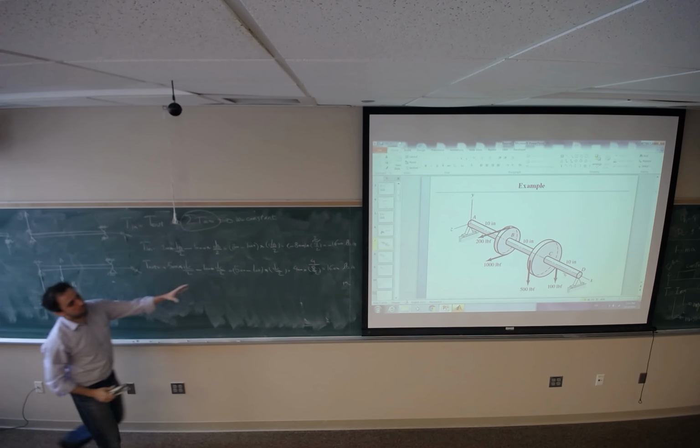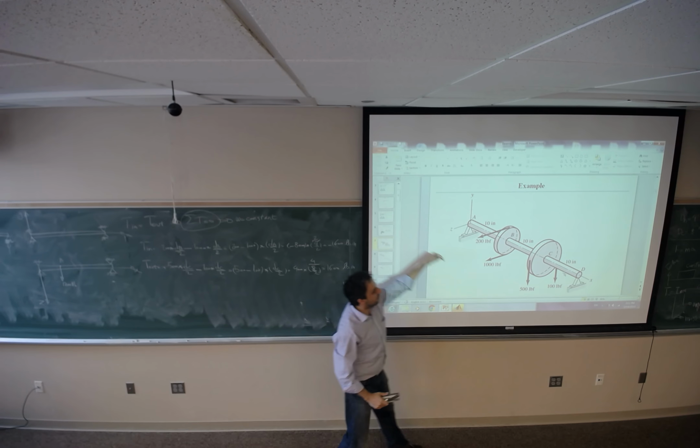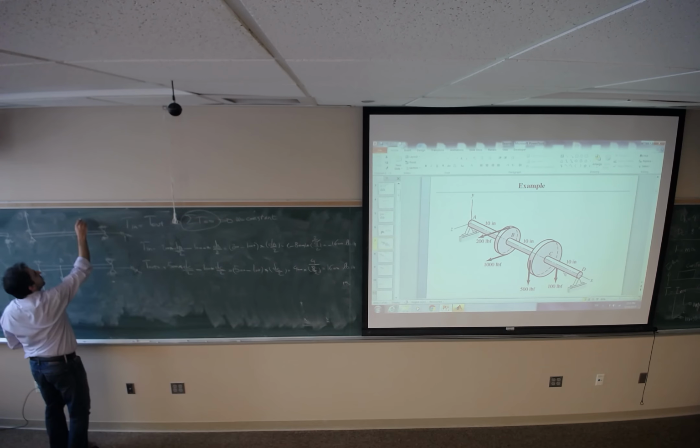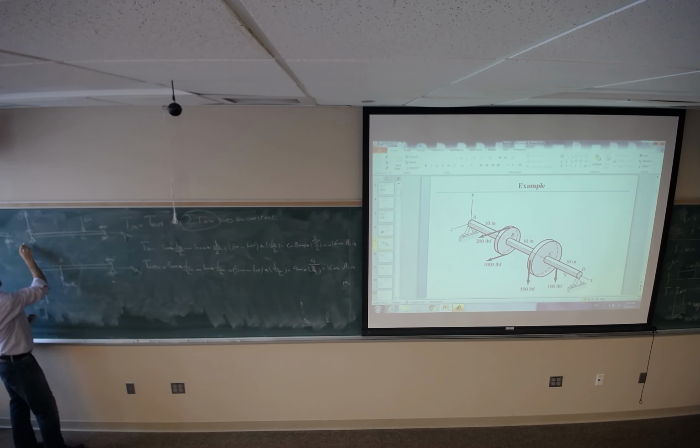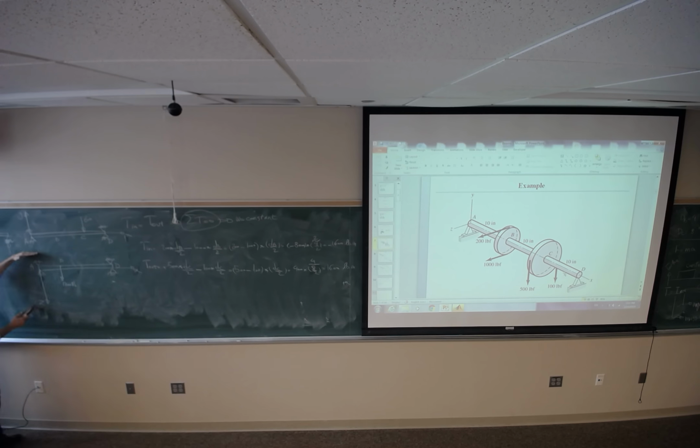I'm looking from this view, Y and X. I will see 600 applied at location C, and A, B, C, and D. So this 1200 occurs at plane ZX. This force acting in plane ZX is making moment about Y. It's going to rotate the beam, or the shaft, about the Y axis.